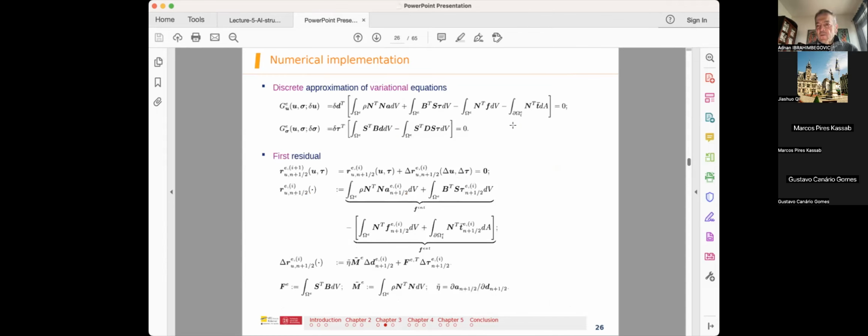So people were doing that before. They were putting in lots of viscous damping to kill it. But basically then you have two types of mistakes mixing with each other. One is wrong interpolation of your stresses, and the other one is putting in some kind of wrong viscosity to kill it, and then the end result becomes something quite uncontrollable. So here we actually enhanced the interpolation so that stresses are really able to remain smooth in the discrete approximation, and then you do not have this artificial introduction of these impacts every time you cross the boundary.